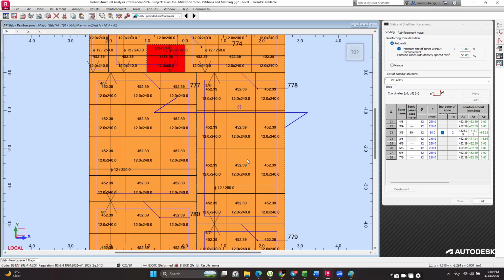So when you're getting very small spacings, say 100, 75 mm, it means that your software is automatically controlling deflection and parameters for the slabs using reinforcement. So what you do at that point is, number one, if the slab depth is small, say 100, 150, I think 150 is the minimum that you can start with, try increasing it to 175, 200, see if the situation resolves.